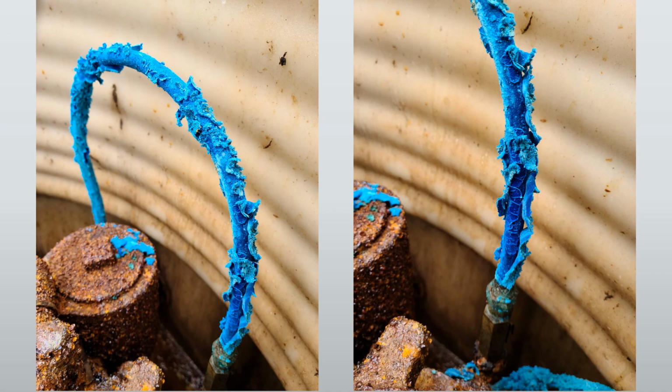Thanks for your time. We've reached the end of the slideshow, and I just wanted to add some fun pictures that I've had over the years that are kind of my Hall of Fame, Hall of Shame, corrosion stuff. Obviously, we're in a turbine sump, so we don't have an electrolyte, but we do have condensation that can settle onto our copper pipe. This is just some great copper corrosion that you can see. We got probably ethanol vapors decomposing, creating acetic acid, causing a rapid corrosion response in some of these turbine sump areas.